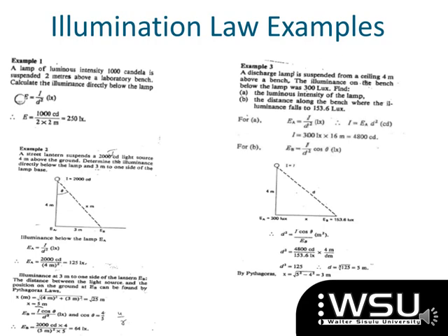So I take that other D to the other side so that I have a D cubed, which means D cubed is equal to the 48,000, that was my I that I got in A, divided by my 153.6, which is the illuminance at that point. I then multiply by my adjacent, and that is how I got the distance of 5.